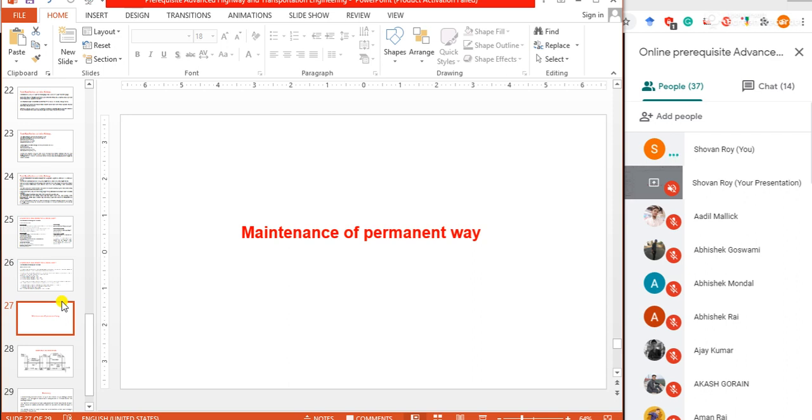Today, about 3,000 km of track is being maintained by measured shovel packing, which is an improved method of manual packing. A need-based directed track maintenance system, which initiates maintenance work only when there is actual requirement, is being increasingly introduced in order to eliminate unnecessary maintenance work. It makes the labor force more productive. About 20,000 km of track is covered by this system.